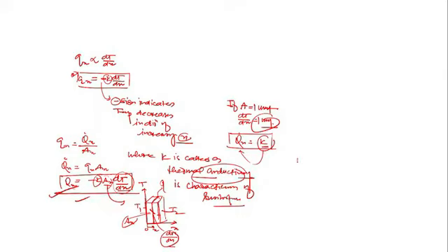Okay, what happens if, let's say, this is the wall, and I'm talking about the x direction here. This axis is temperature. If the profile is linear, if dT/dx is constant, what is the meaning of constant? In which case it is constant, I will discuss later on. Let's say this is the wall through which heat transfer by conduction is taking place, and dT/dx is constant. Then by Fourier's law, if dT/dx is constant, and here temperature is T1 and here temperature is T2, in this case you have also seen the area, actually this is the material in this way.